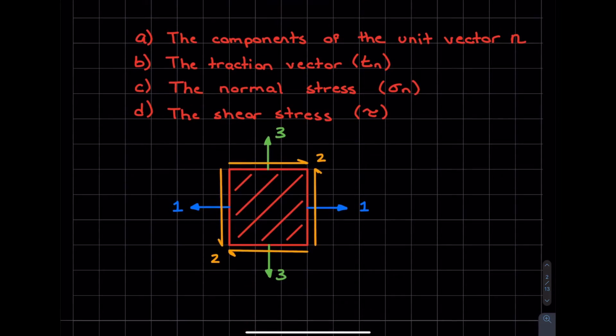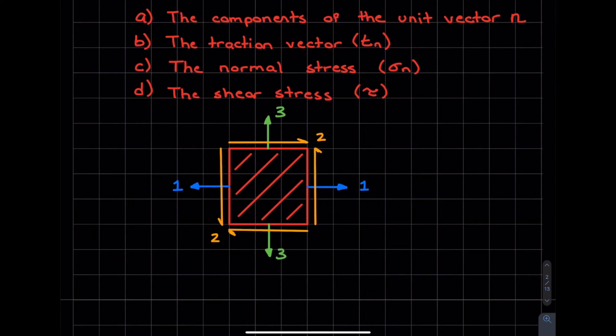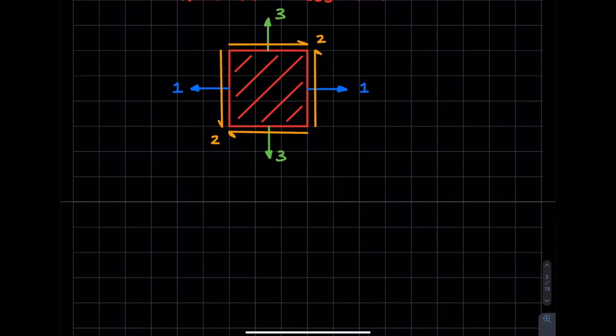So if we look at this question, we're given this stress state, and I'm really trying not to say stress state, stress state. The question becomes, okay, what is my sigma matrix? Because if we have the sigma matrix, then everything is pretty easy. But the problem is we don't really know what exactly it is. So we're going to come down here and say, okay, well, remember, this is going to be two-dimensional. So my sigma is going to have 4 components with basically 3 unknowns because we know that it's a symmetric matrix. So if we know sigma 1,2, we also know sigma 2,1.